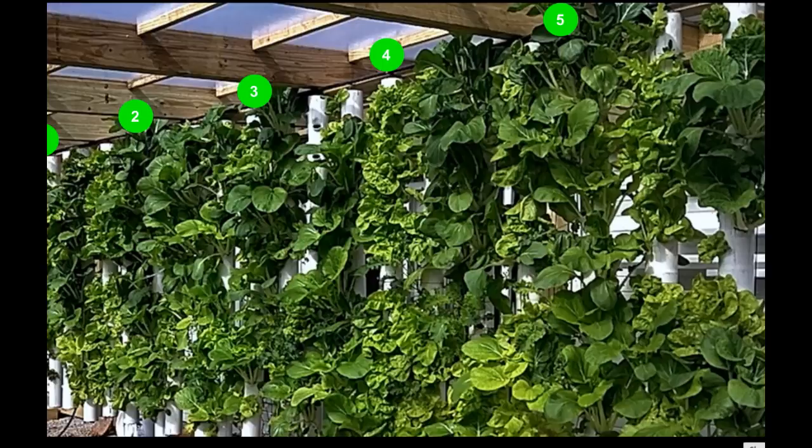towers at a time, and the thing to note is you have one pump pumping a bunch of different on-off switches for water, so the water can go into the different towers, but you're using one pump. You're turning on different sets of the towers at a time, so that a single pump now can run just a small number of them, like say 4 towers per pump.